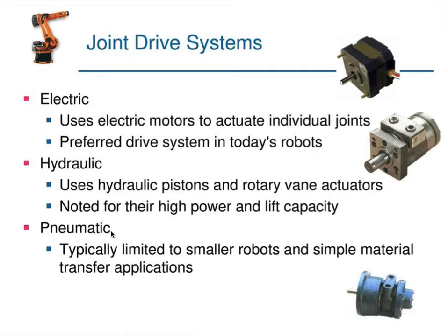Coming to pneumatic drives, they are typically limited to small robots and simple material transfer applications only. If you see these pneumatic actuators, there are linear and rotary pistons, and pneumatic actuators are smaller and technologically less sophisticated than the other two types.